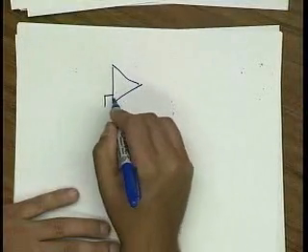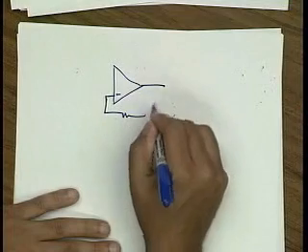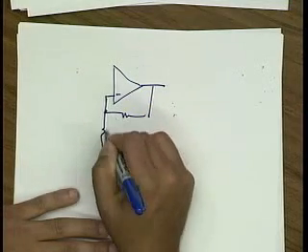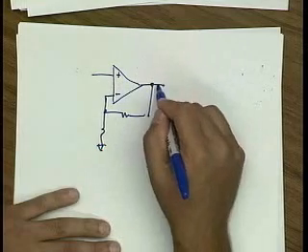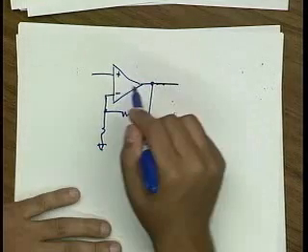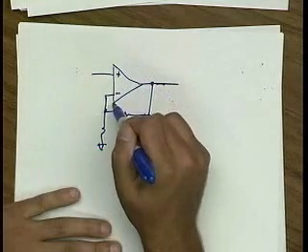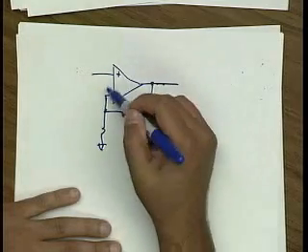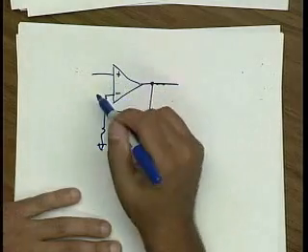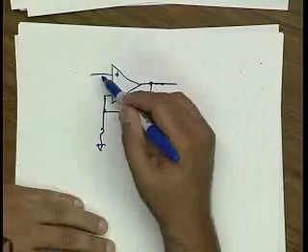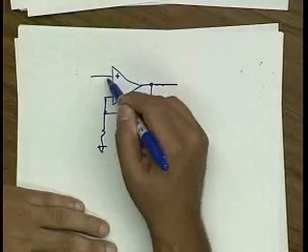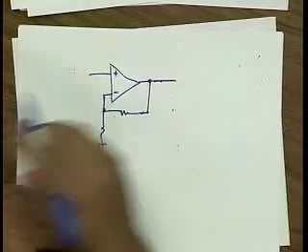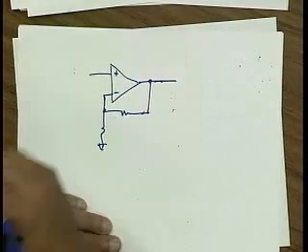Let me just take a very simple example. What the op-amp is doing is it's taking the output, subtracting it from the input. It's basically trying to make this input signal very small, right? Ideally with infinite loop gain, it makes the input signal 0. And so if the input signal is very small, we know you generate less distortion. So that's one way to look at it.